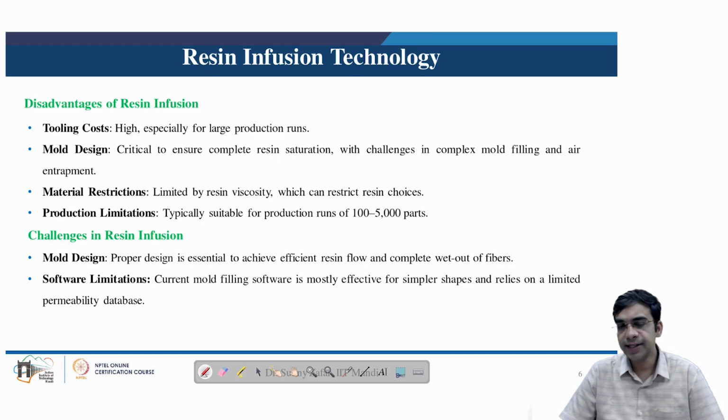There are several challenges also in the resin infusion technology, which involves the mold design. Proper design is essential to achieve efficient resin flow and complete fiber wet out. Software limitations are also currently in place because the current mold filling software is mostly effective for simple designs and relies on a simple permeability database.